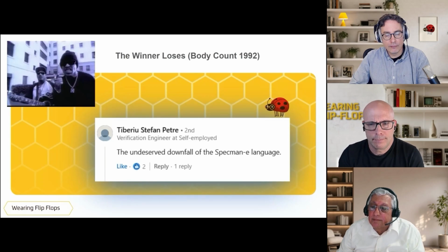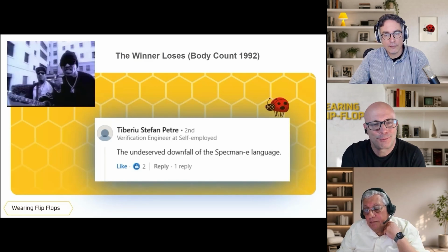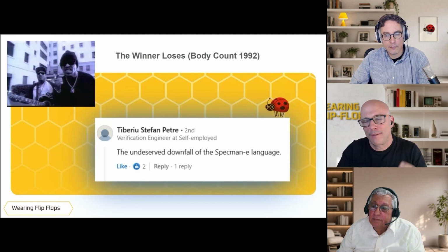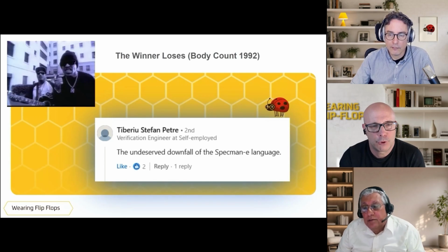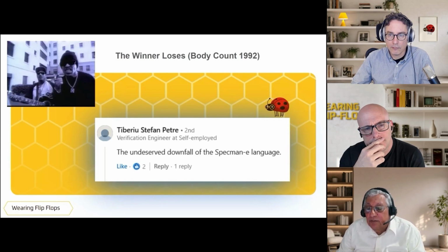But a question that we wanted to ask you: if you were to start a new verification project today, having said everything that we just discussed, which language would you have chosen, and why? I would choose SVTB, the UVM Verilog, from now, because of the practical reasons that you mentioned so far.